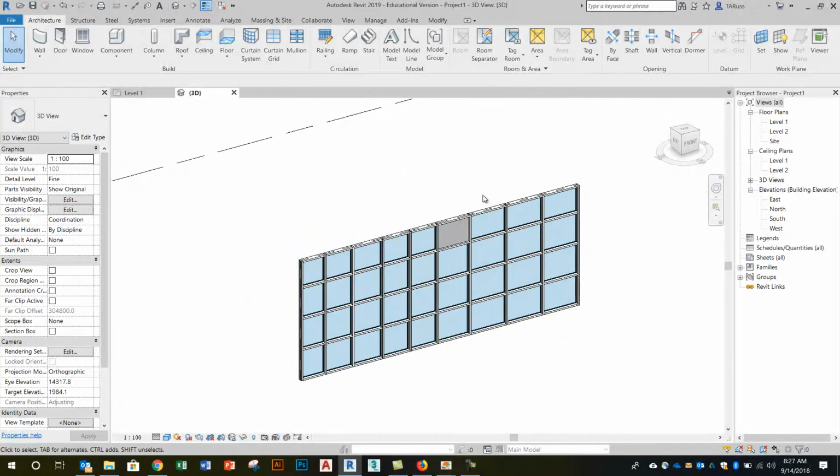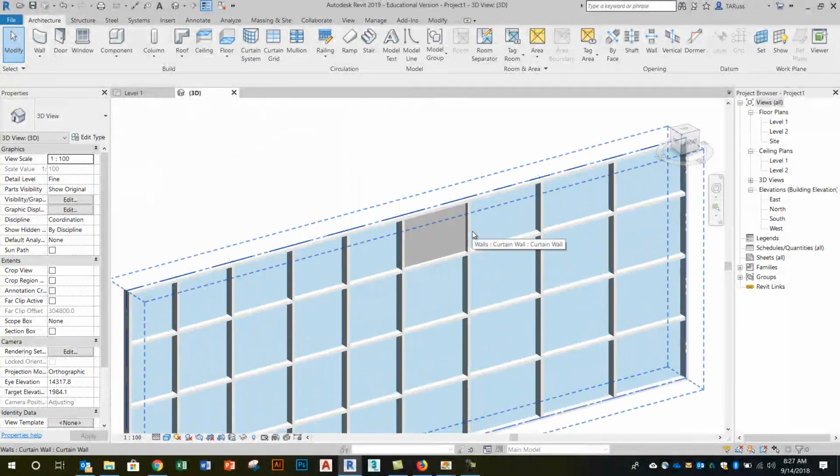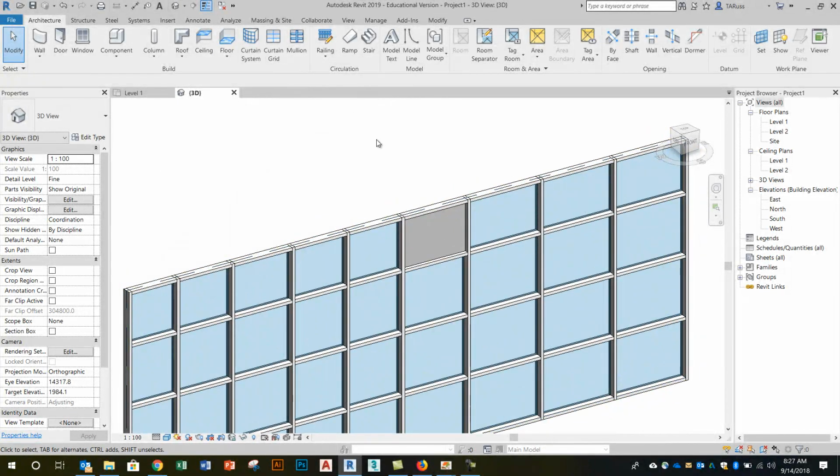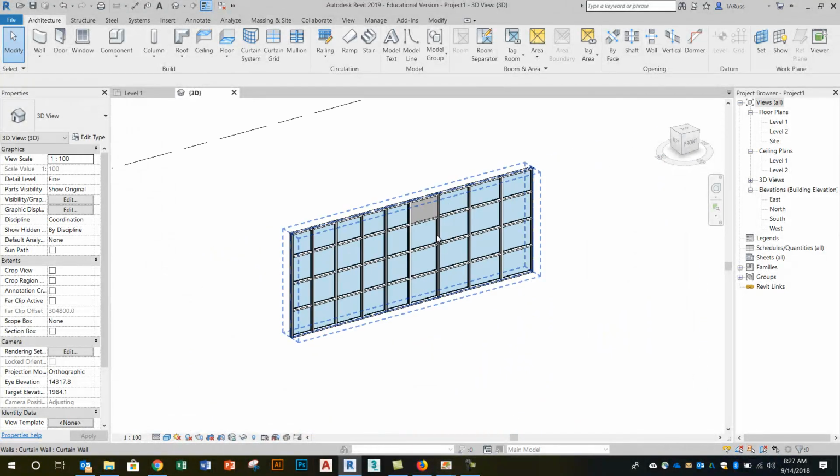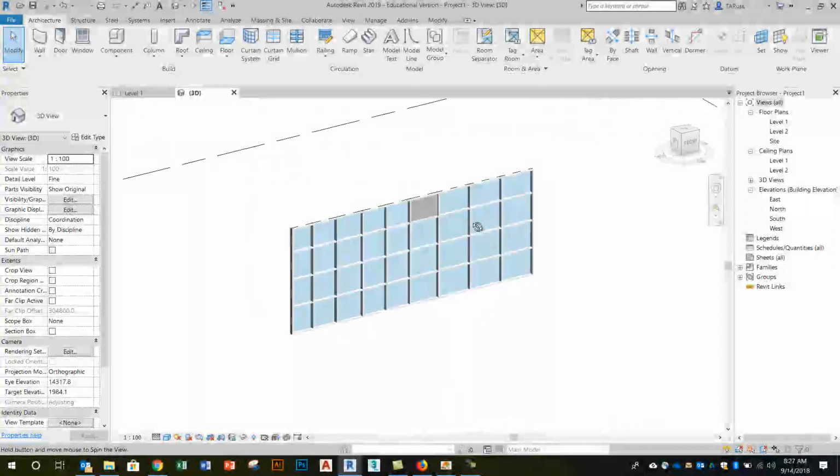All right, so remember your selection sets. As I said, the tabbing, or select a batch or a set, and then use your filter tool. And that's how we make selections on these really difficult, complex objects.